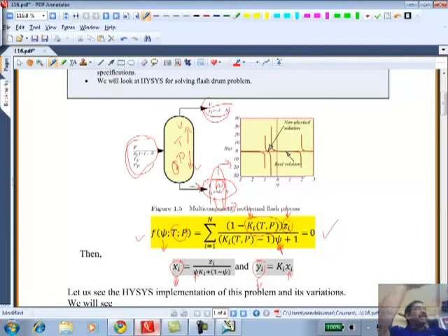So you just cut and paste that part of the MATLAB code to solve a second stage, but redefine your feed condition to be the output condition from the first one. So it is not very difficult to extend this in MATLAB to solve two equations. But the thing that you need to realize is that it is a sequential process. They are not coupled. You can solve the first stage independently, take the output, feed it to the second stage, and solve that independently using the same mechanism that you have used for the first stage.